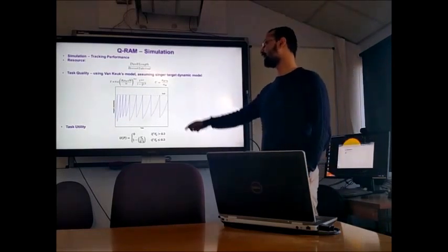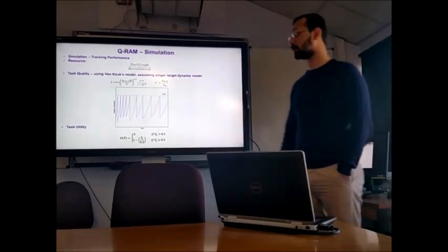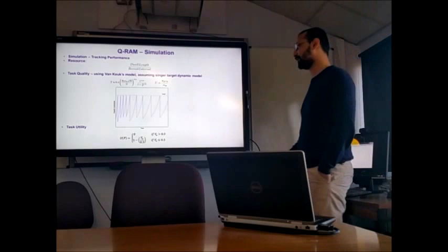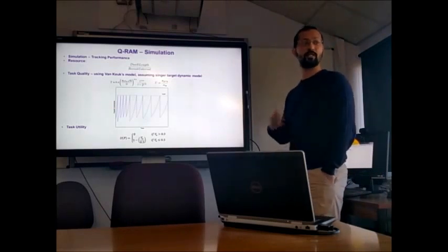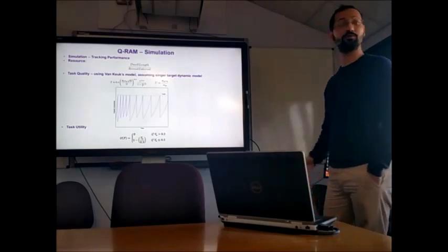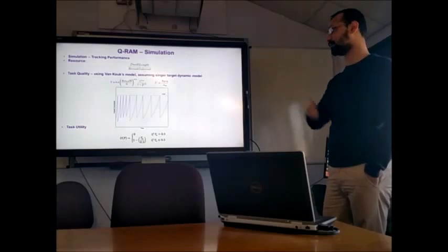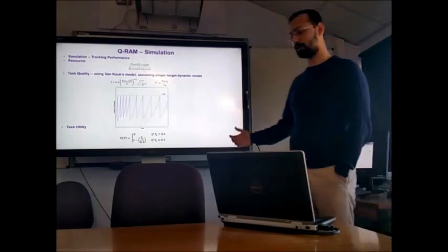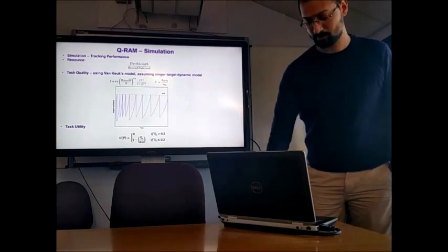And then I've defined my task utility function, as you can see here, where VE is our estimated track sharpness. In literature, it's been defined that if the track sharpness exceeds 0.3 of your beam width, then most likely in practice you will lose track of that target. So in our utility function, we incorporate that as 0 utility if we are greater than 0.3 of our beam width in terms of track sharpness.